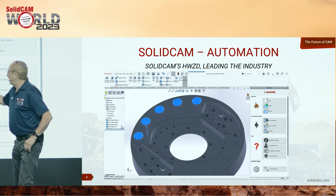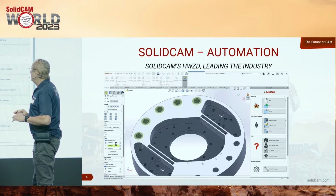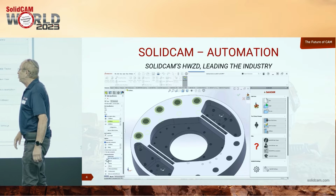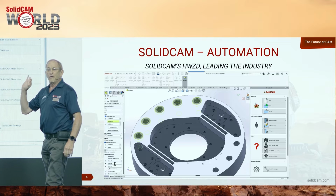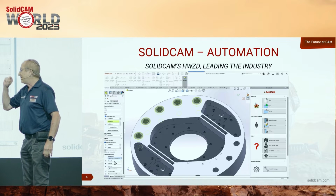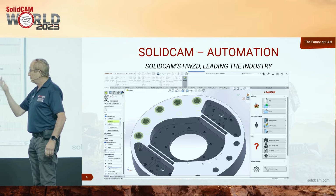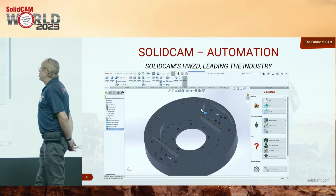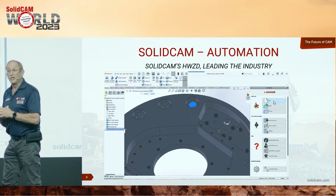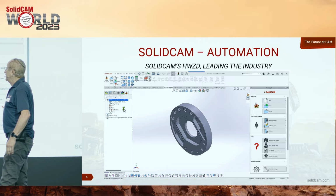If you take a look right over here, I'm just going to take the counterbore hole that we have, for example. If we look inside, this is a 17 millimeter through hole with a counterbore of 32 millimeters, but both of those dimensions have tolerances, a 0.2 plus and a -0.2. Now, if we take a look at the actual through hole itself, it is still a 17 millimeter hole. So it's an actual dimension, but all we have is the tolerances.